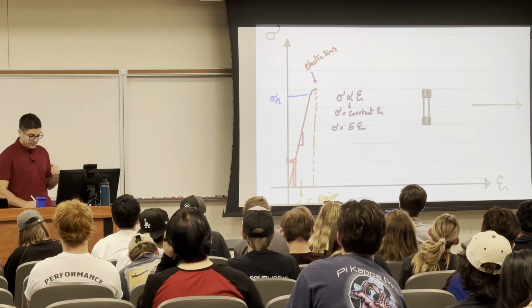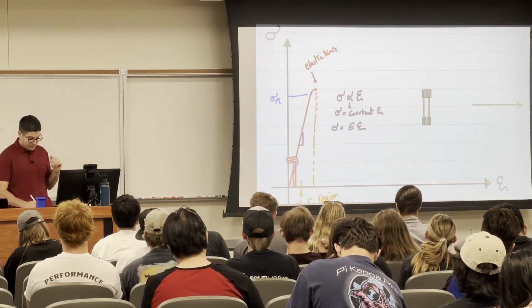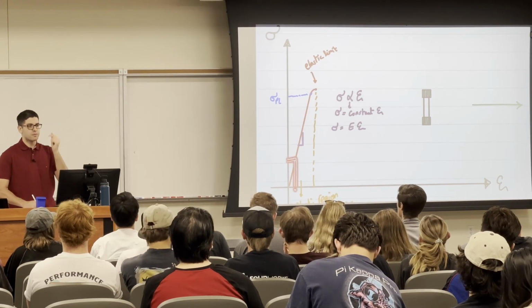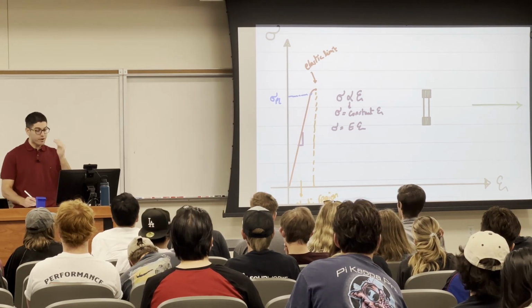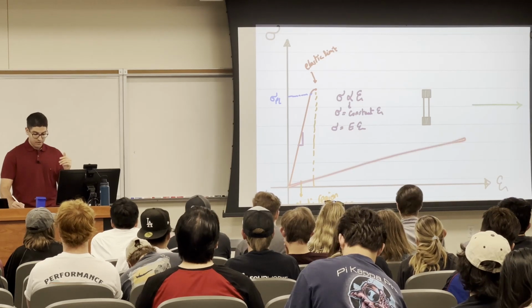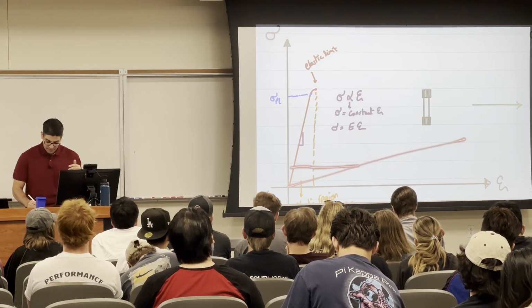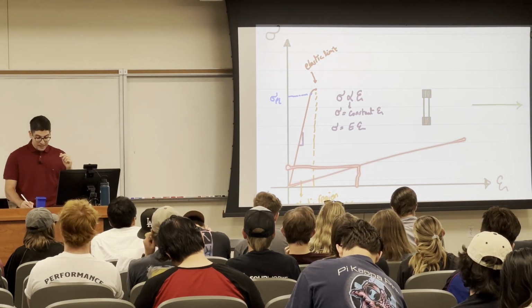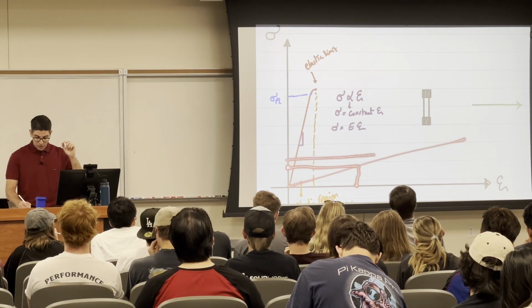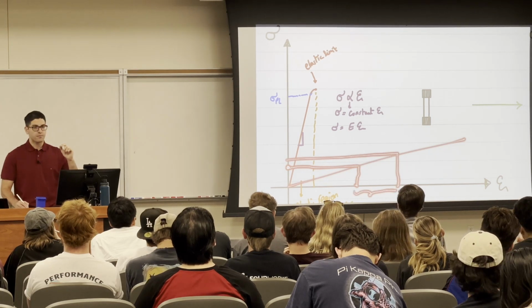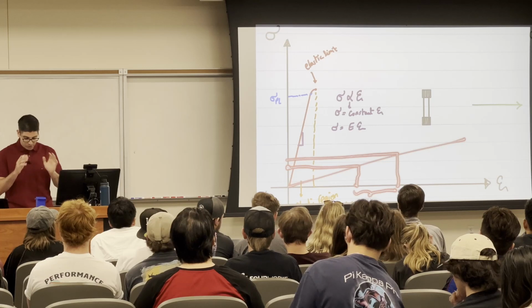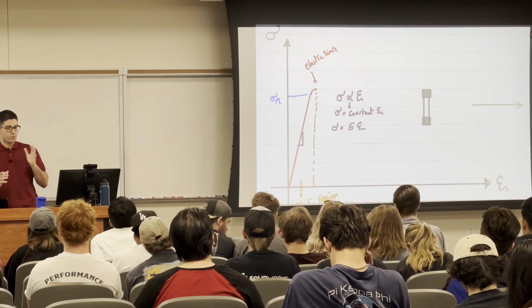If I increase the stress a little bit, this is the deformation. There's barely a difference between them. But if you have a material that has lower E, it's going to be something like that. If I apply a stress here, for example, this is the deformation. And if I increase the stress a little bit, you see the difference in strain, it deformed, and you don't want that to happen. Or, for us as civil engineers, we don't want that to happen.